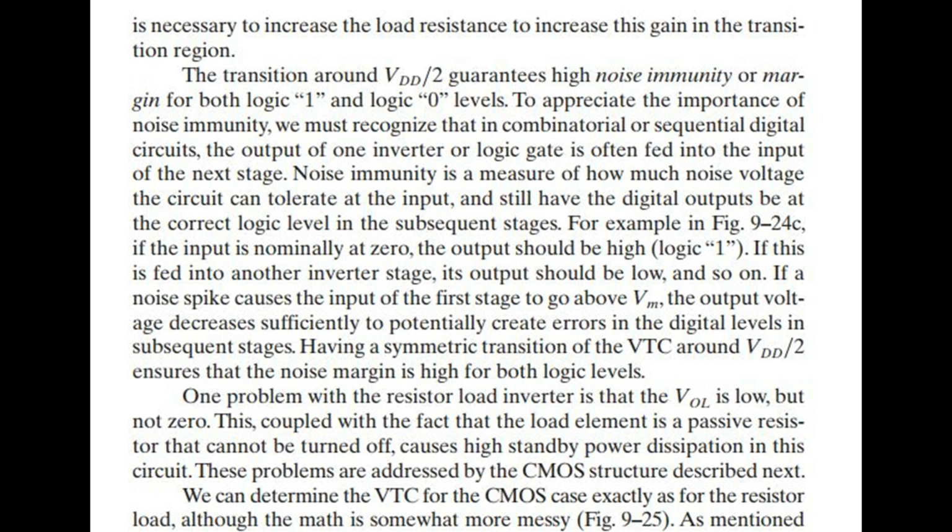High gain guarantees a high-speed transition from one logic state to the other. It is necessary to increase the load resistance to increase this gain in the transition region. The transition around VDD/2 guarantees high noise immunity, or margin, for both logic 1 and logic 0 levels.